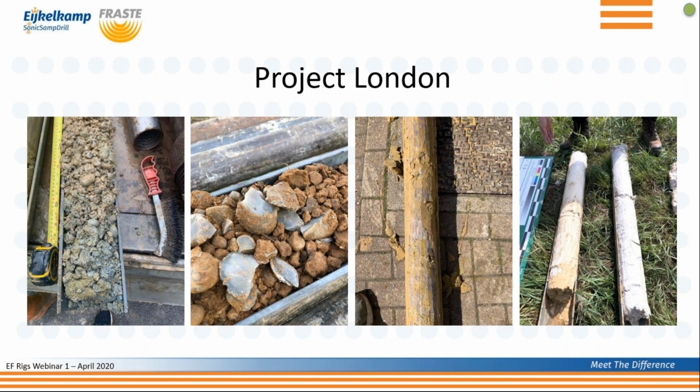And then the last picture we see over here is a chalk material. How did you core that before with cable percussion? Normally, when it's dry, we'll cut it out with a cutter or a stubber, which is lifting the tool up in the air and dropping it from great height to punch into the ground, then pull it out and knock it out with a hook or a crowbar.